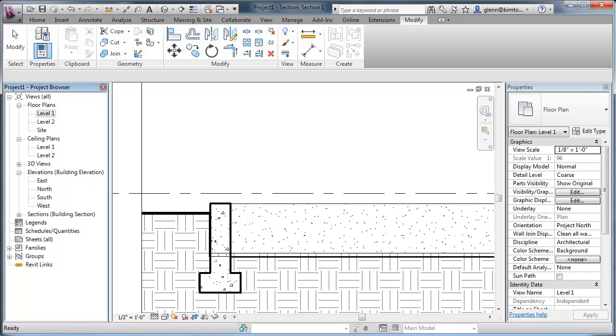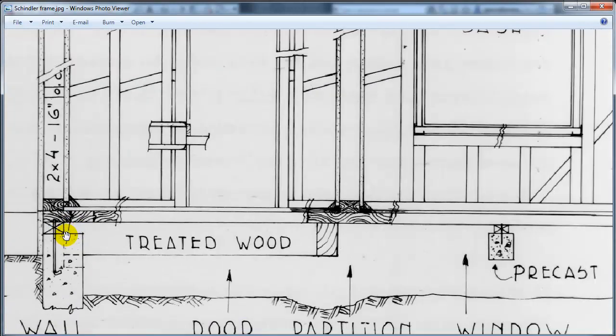I basically want to think about that base plate, and if I go back over to the detail and take a look at it, it's pretty much a 2x4 laid flat, is what we call it. So 3.5 wide by about 1.5 inches tall by today's standards, a little bit bigger when the house was actually built. But if we were going to model that, I'd probably take a profile and sweep it around. That'd be the easiest way. I could model it as a bunch of individual sticks, like individual beams, and put them on top there, but that might be even a little bit more work. So I'm going to just do it as a profile, because I think a swept profile might be the easiest way to get a quick approximation.